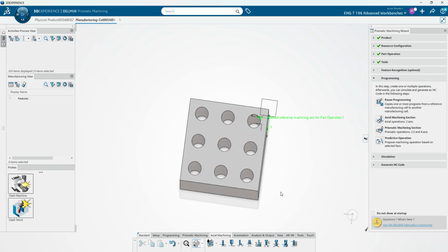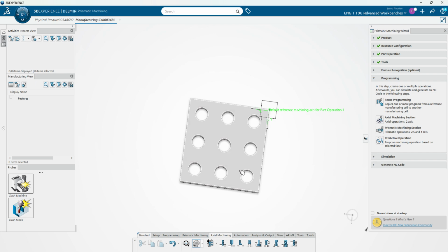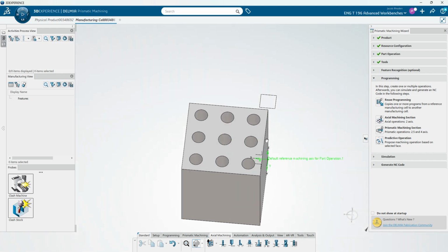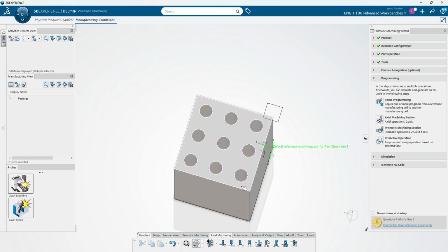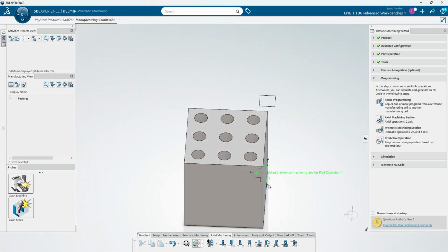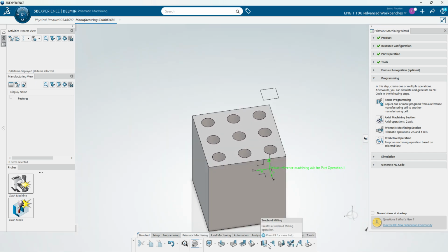It's also good if you have a large diameter thread. And this will take that thread mill and run it around the inside of that hole, just milling those threads into it. And then here we also have circular milling, which would be making a hole but just using an end mill instead. So maybe if you have a hole with a bigger tolerance and you don't want to go through the process of having to pull out another drill, because you can just really quickly bring it in. And then sequential drilling or sequential groove operation. And those are pretty much the drilling options we have in here.